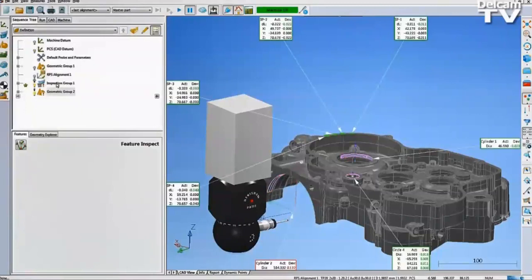Here, one thing you can remember: your software always has to be online, connected with your CNC CMM for the inspection. Apart from that, the programming technique, if you want to generate the inspection sequence, or create the geometric inspection or surface inspection, the same method is applicable on OMV also. From a programming point of view, the generation of the features and the inspection points are very similar. Nothing is different between the two applications, but here your software has to be continuously connected with the machine for the inspection, whereas in OMV your software will generate the NC code and it will be run on the machine. So these are the two basic differences between CNC CMM and OMV.